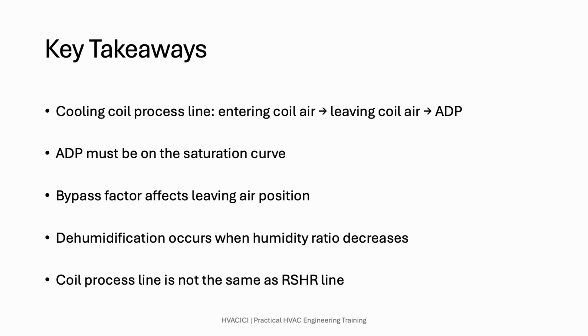The key takeaway is that cooling and dehumidification should be understood from the coil process line. ADP belongs to coil interpretation. The leaving air point depends on coil performance and bypass factor, and the coil process line should not be again confused with the RSHR line.